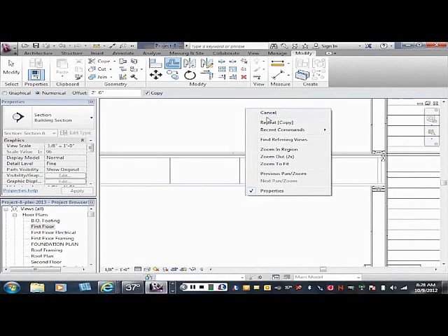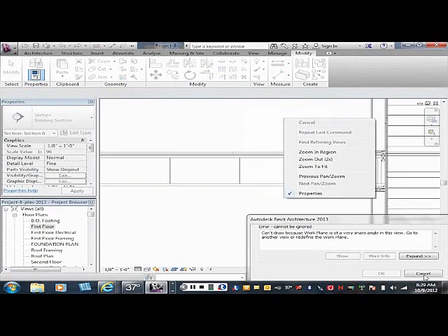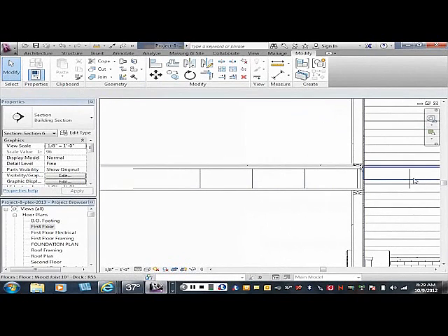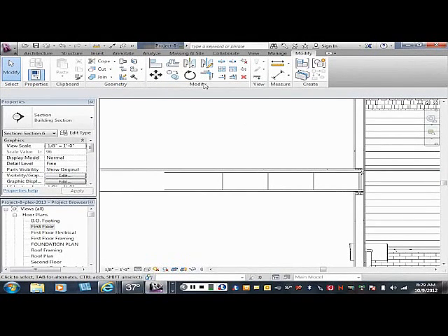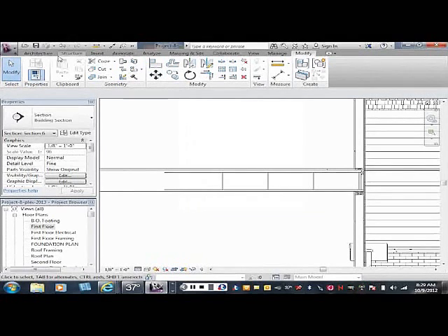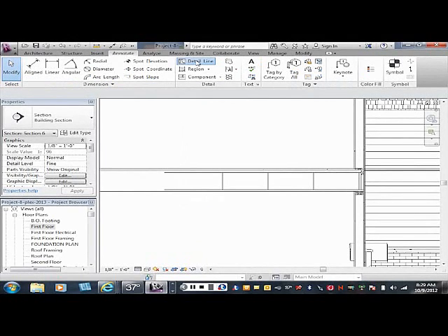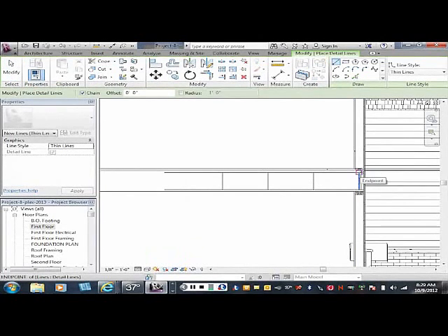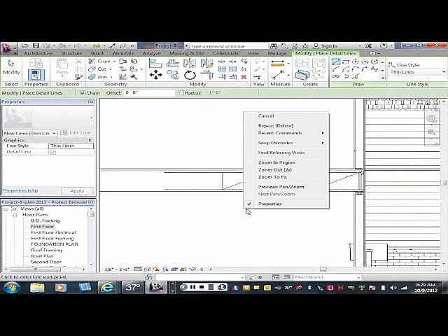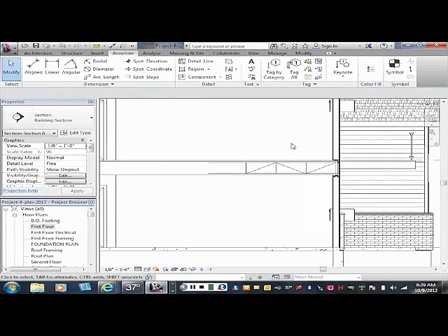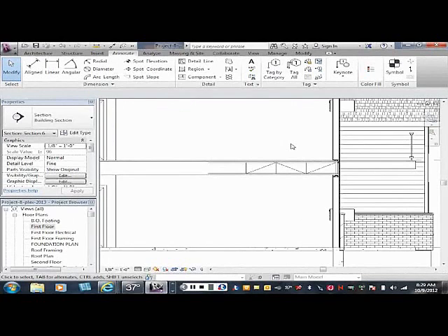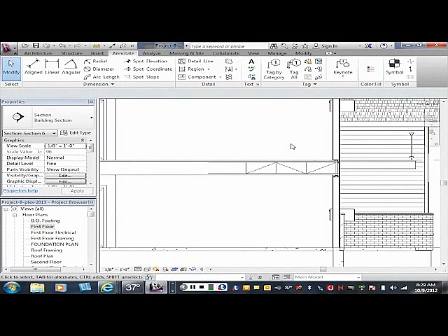Okay, so I've offset some lines 30 inches apart. Now I would draw another detail line from the intersection here to the intersection here, and so on. So 30 inches apart, thinking about that, if this truss was 14 inches deep, that would be one angle. If this truss was 24 inches deep, that angle would be different, right? They're still 30 inches apart, but the deeper the truss, the steeper the angle gets to be.